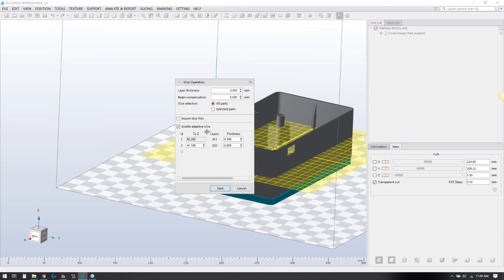What that would do is you would consider doing this as if some of your parts are very vertical and you want that part to print really fast and you don't care about the resolution. But then at another part, you want it to be very high resolution because it's a lot of organic shapes. You could adjust the height for that. Some really cool stuff.